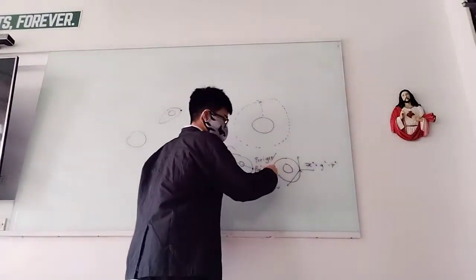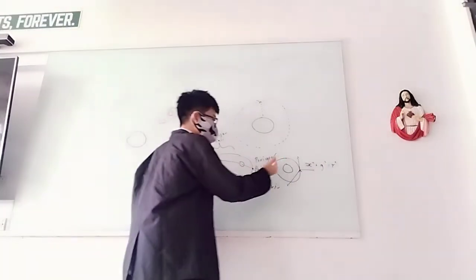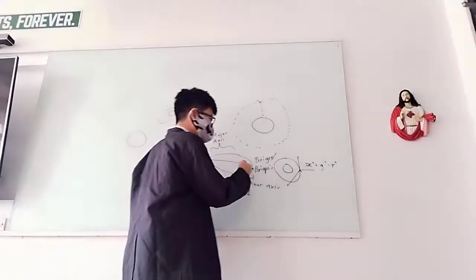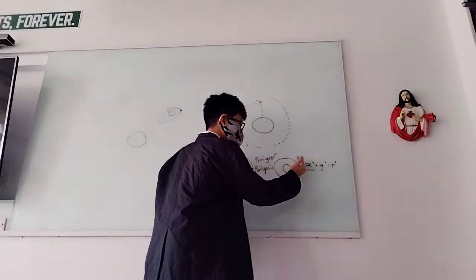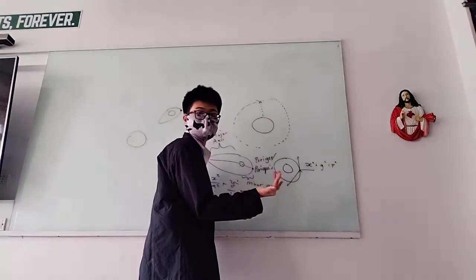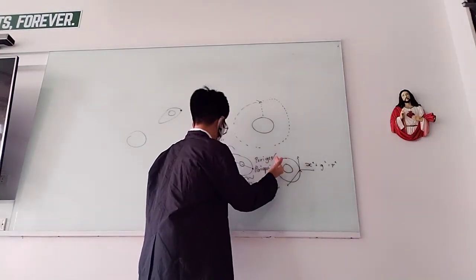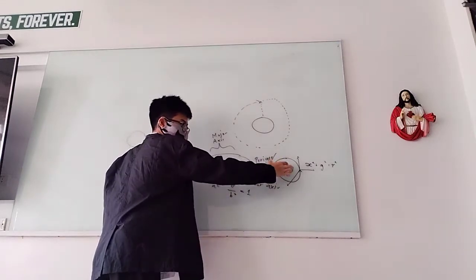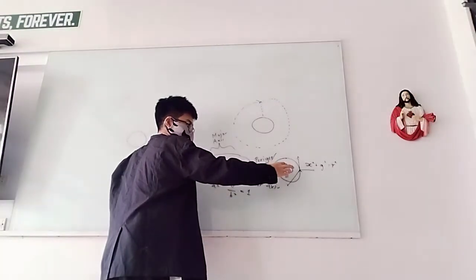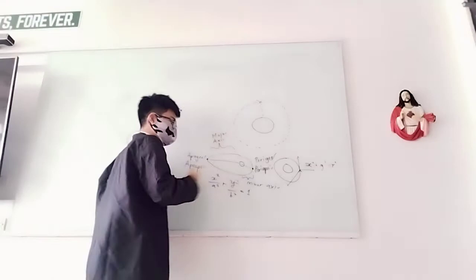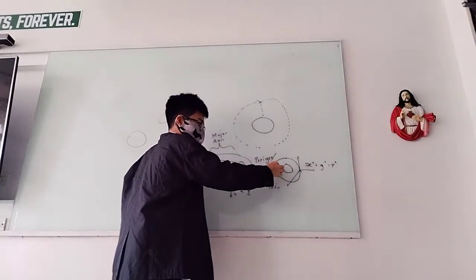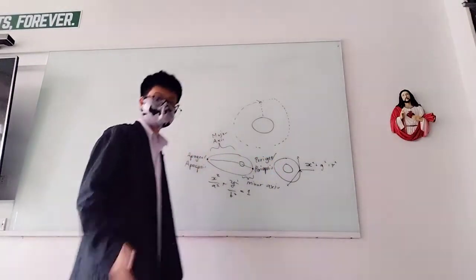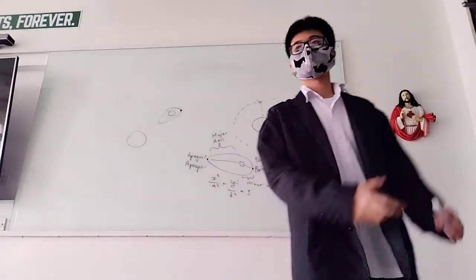If you burn your fuel in the direction of your velocity vector at your periapsis or perigee, your apogee, or apoapsis, is going to increase. The distance between your apoapsis and the planet's center will increase, and that means you're going faster.